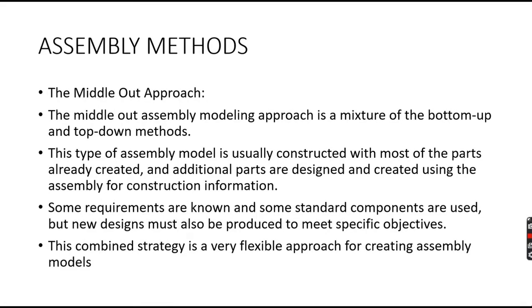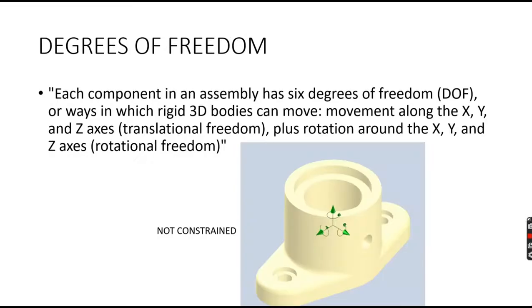The middle-out approach kind of uses a mixture of both. This type of assembly model is usually constructed with most of the parts already created, and additional parts are designed and created using the assembly for the construction information. It's very flexible for creating assembly models.